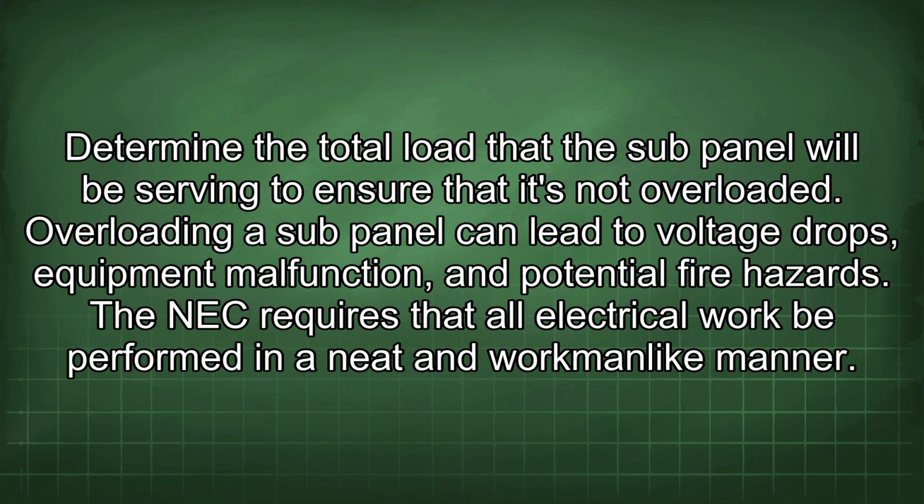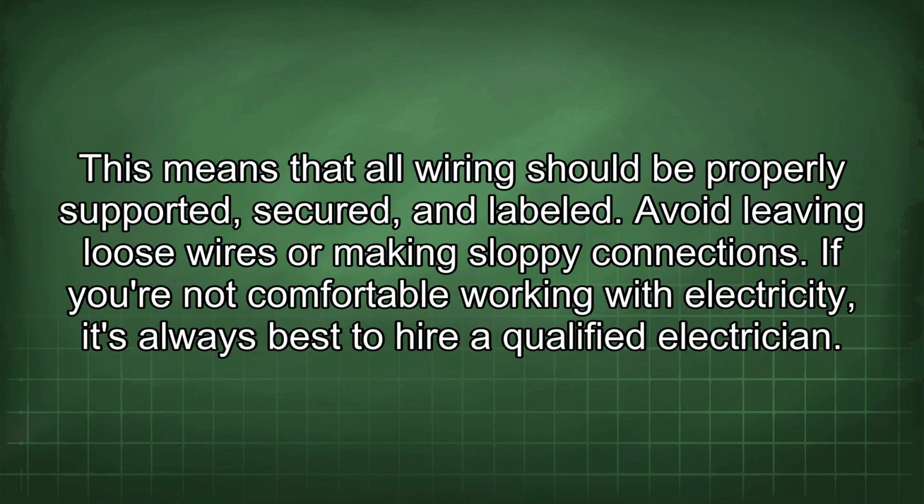Overloading a sub-panel can lead to voltage drops, equipment malfunction, and potential fire hazards. The NEC requires that all electrical work be performed in a neat and workmanlike manner. This means that all wiring should be properly supported, secured, and labeled. Avoid leaving loose wires or making sloppy connections.